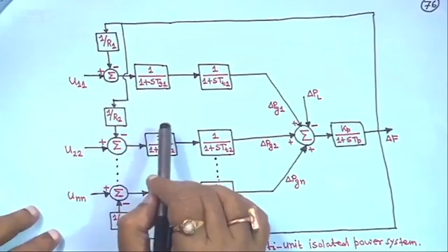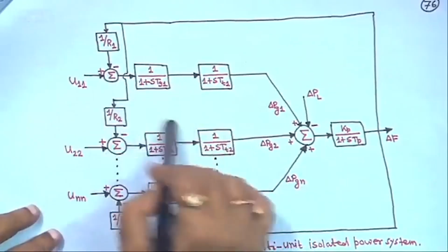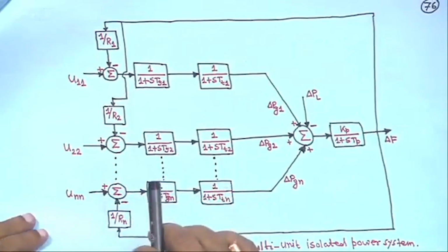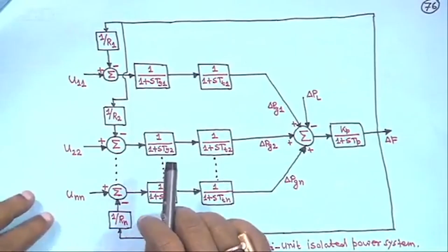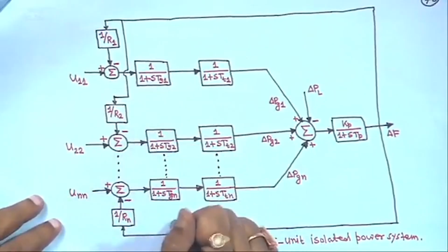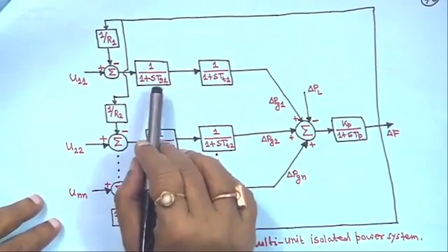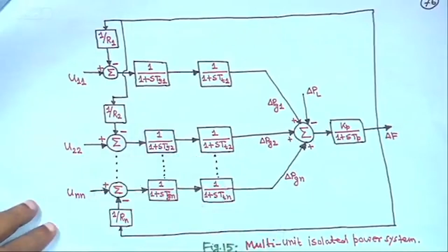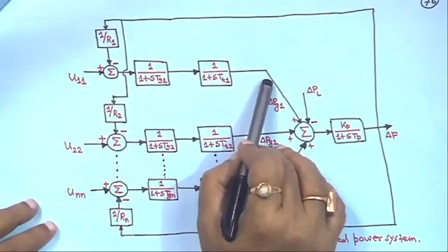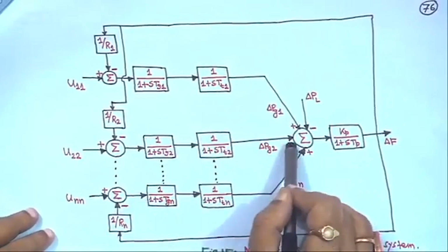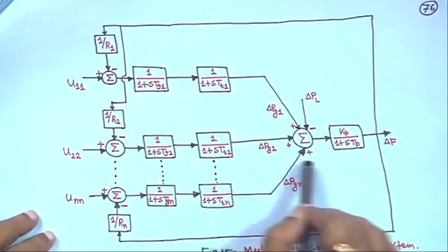Those things I will not cover, but giving some ideas, every governor has a dead band, right. Dead band means the magnitude of sustained speed change within which there is no change in the valve position. So, the dead band is there. If you consider the governor dead band, it has some mathematical analysis, but here we will not consider it. If you put a generation rate limit and a governor dead band, then in the response you will see a very long sustained oscillation.